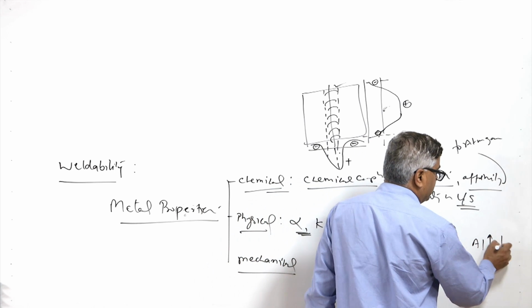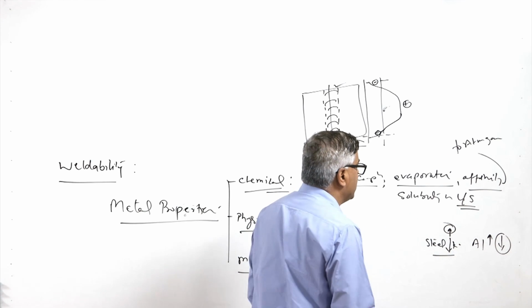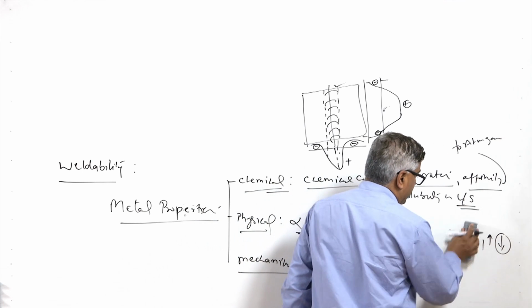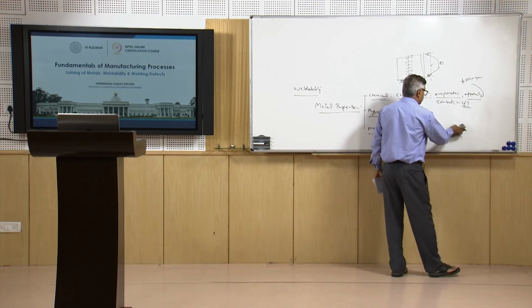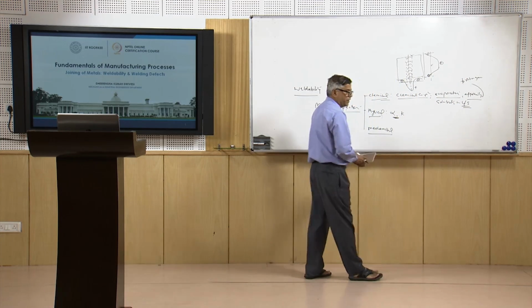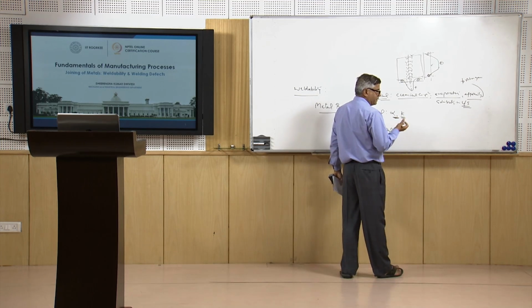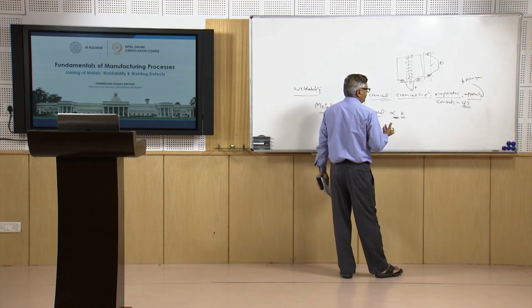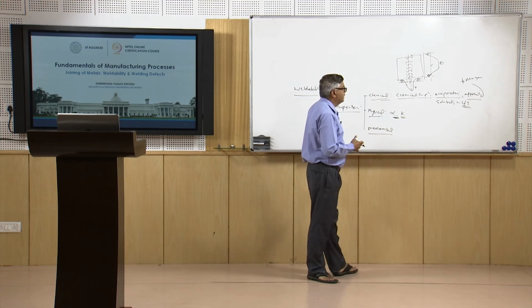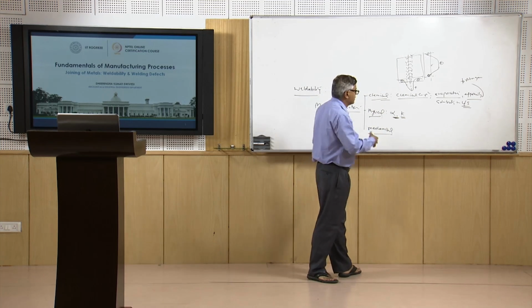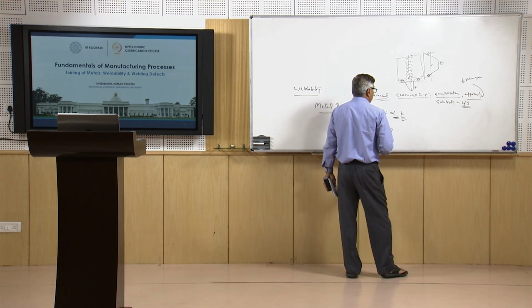So, it will be leading to reduced weldability, because it will be transferring the heat easily from the region where heat is being supplied. So, it requires a lot of heat to be supplied during the welding. It requires higher welding current, like in welding processes such as electrical resistance spot welding, where if we compare steel and aluminum, then aluminum needs much higher welding current as compared to steel, primarily due to the thermal conductivity related aspect.